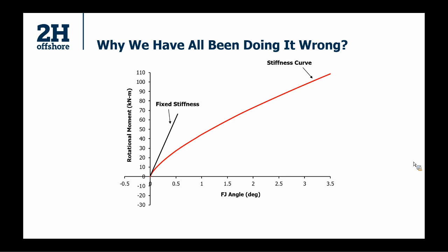As we mentioned earlier, the actual flex joint breakout stiffness is hysteretic. With small loading, after the curve deviates from its initial nonlinear curve, as shown in this blue loop, the unloading and reloading path will form a hysteresis loop around zero flex joint angle and never follow the initial curve.